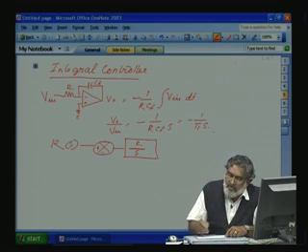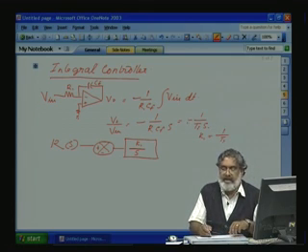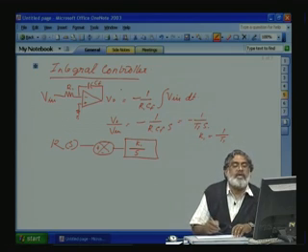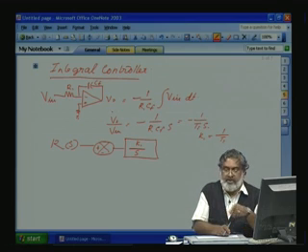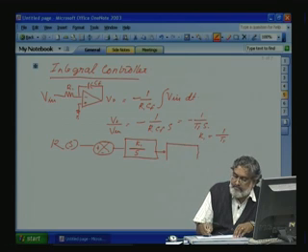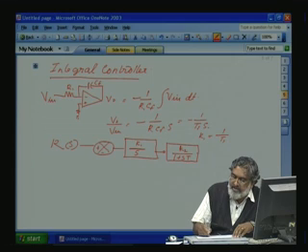Okay, forget about the negative sign, that we can correct with another inverting amplifier here. So, K1 is equal to 1 by Ti. So, integral representation is K1 by S. Again, let us take a first order plant, K2 by 1 plus S tau. So, we are giving feedback here.